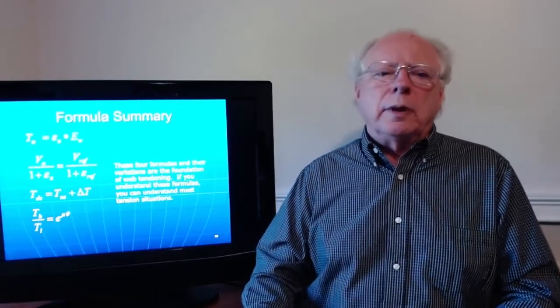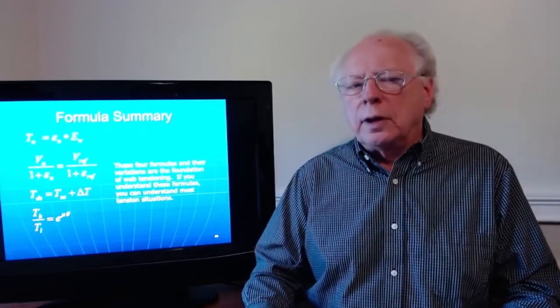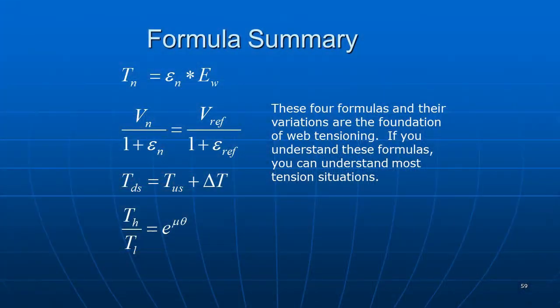So formula summary then. We've done all of this so far with 4 formulas. Tension equals strain times web modulus, the strain transport formula, the idler drag formula, and the capstan formula. Just about anything that you do in web handling can be modeled with these 4 formulas in steady state. And so you might modify them a little bit for a very specific case, but especially the idler drag and the capstan formula, but 4 basic formulas cover just about everything you can do in web handling.